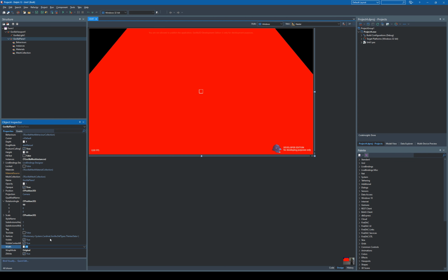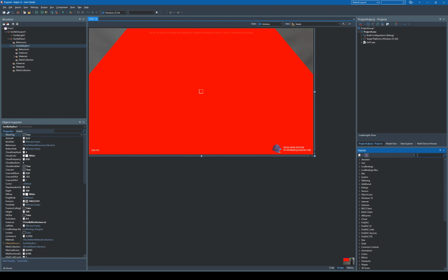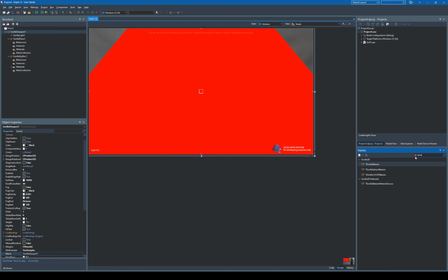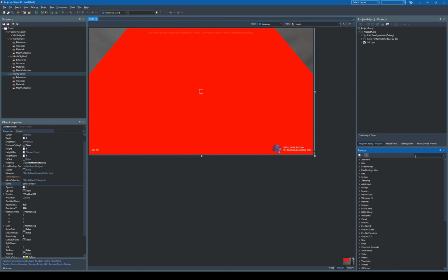To make our scenery more exciting, let's quickly add a procedural skybox with the default settings. And we also add a terrain to test our reflections and refraction. Set the depth to 20 and the width to 20. And we set the height scale to 3. Then we move the terrain on the y-axis to 0.5.